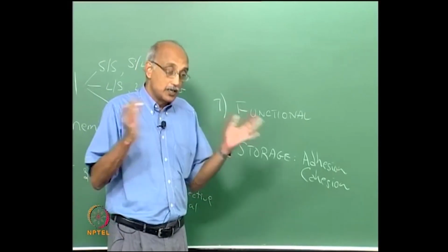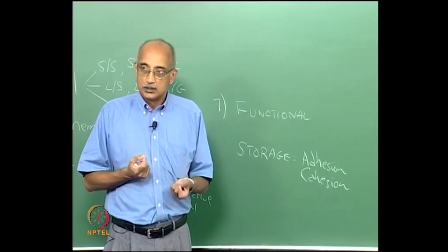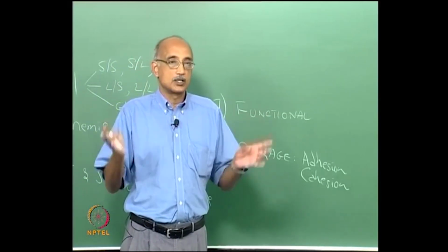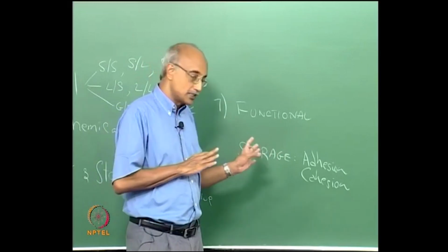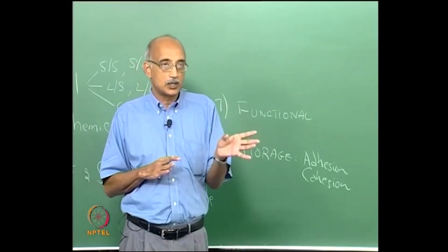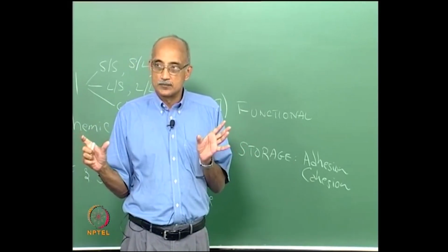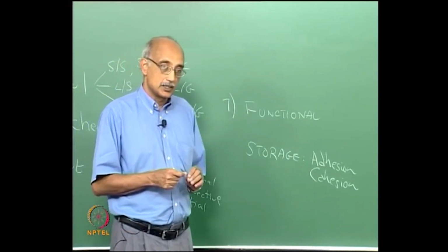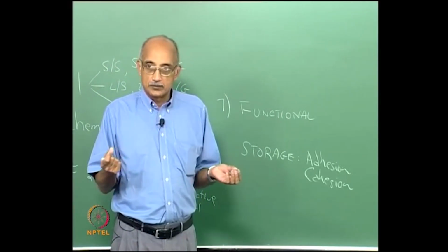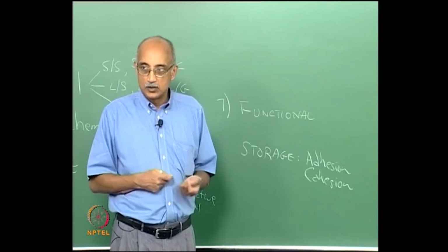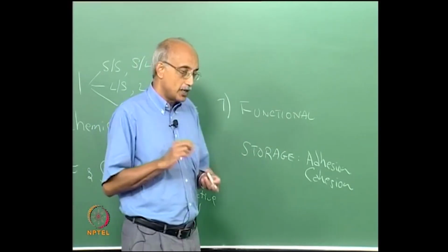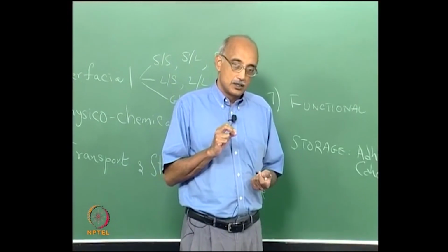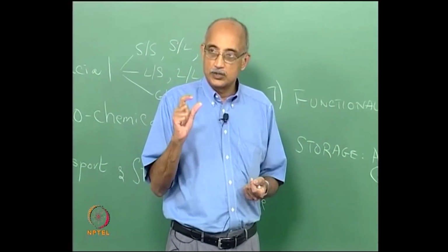also in terms of bulk properties, things like repose angle or the contact area between adjacent solids, all of these are characteristics of particulate assemblies. Another way we will later classify virtually all of these characteristics is as single particle characteristics and particulate assembly characteristics. The way that a single particle behaves is the fundamental starting point, but in many cases in real life you do not deal with single particles in isolation, you are always dealing with collections or assemblies of particles. And when we talk about describing the characteristics of a particulate assembly, in many ways it is a simpler task than characterizing an individual particle.